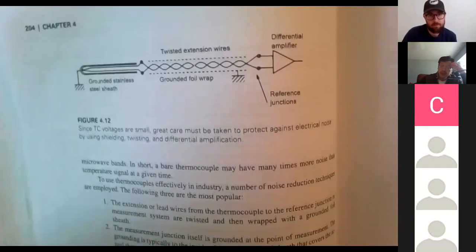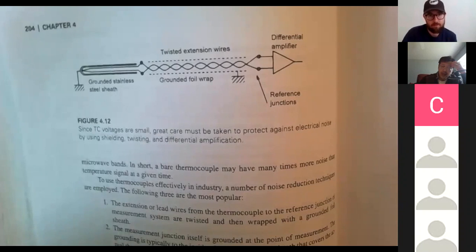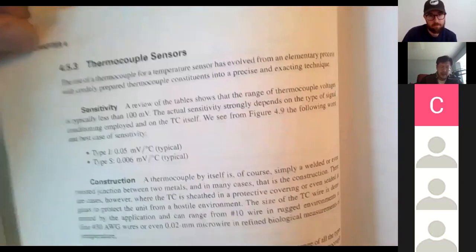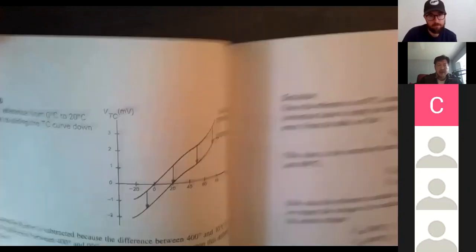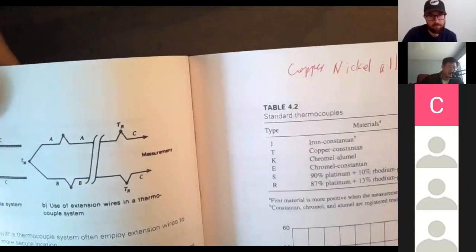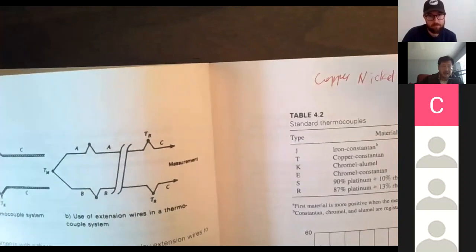It is called a thermopile because a single couple is not powerful enough. The voltage is 20 milli, for example. So you have a couple of them; we don't call it a thermocouple, we call it a thermopile.